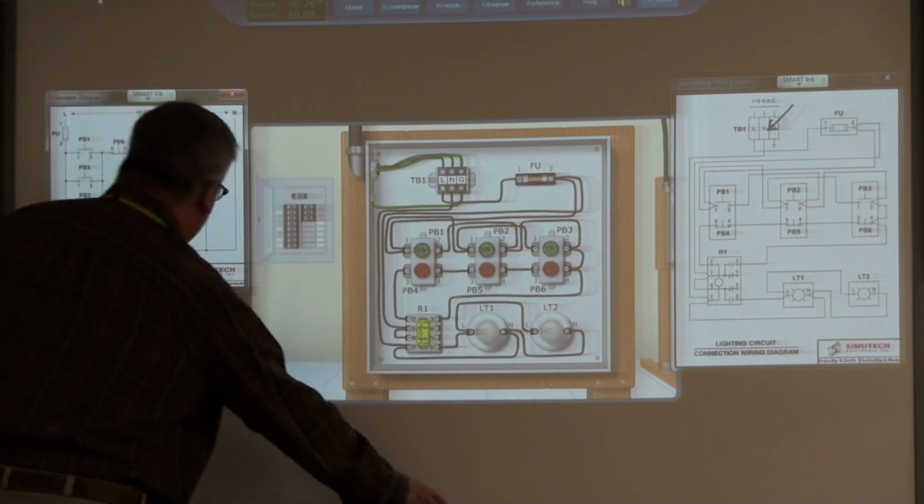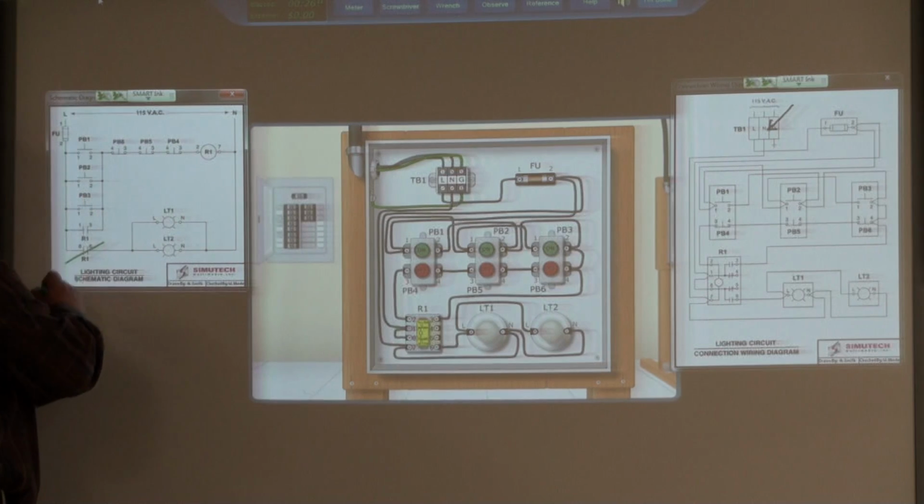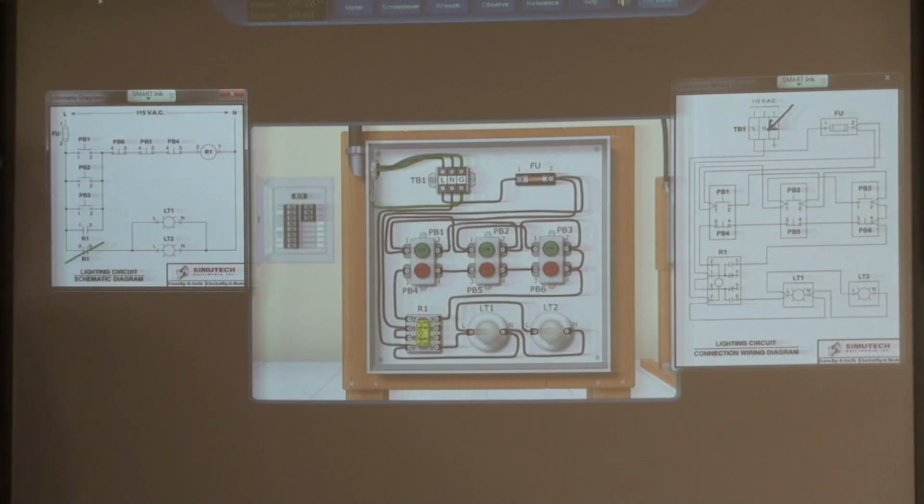Okay. All right, let's take the other guy. This contact welds itself closed. Symptoms: can't turn it off. Lights are on right now, can't turn it off. All right, so what's the only way I can turn those lights off? Unscrew one of the off buttons. Any of 4, 5, 6, 7. As long as I press one of those buttons, for the instant that that button is pressed until I return it back to its normally closed state, we're gonna see these two lights remain on.